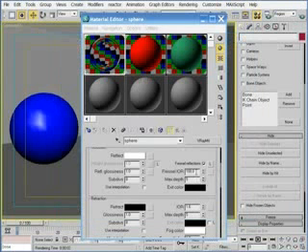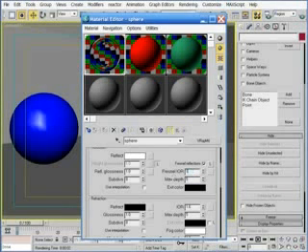My point in demonstrating these ridiculous values is that Fresnel effects really only work when you use a value of greater than 1.0 and less than 2.0. If you do, this is really a wonderful way to add a touch of realism to certain types of objects in your scene.